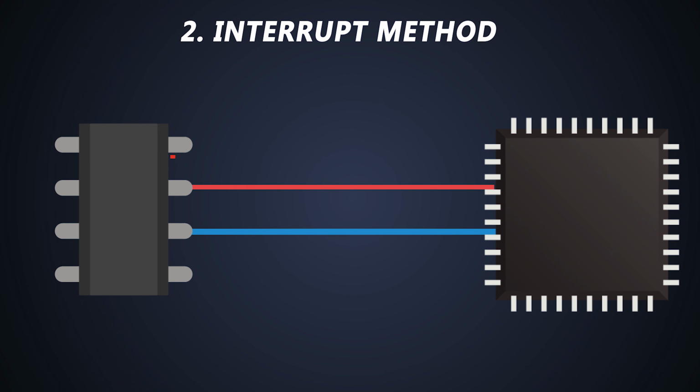In interrupt method, we don't need to monitor the status continuously, because when the data is received or transmitted successfully, a particular interrupt is generated in the code, to which an interrupt service routine will respond. So, interrupt method has advantages over looping method because our code doesn't get stuck at the same place. We can complete parallel actions in the system.